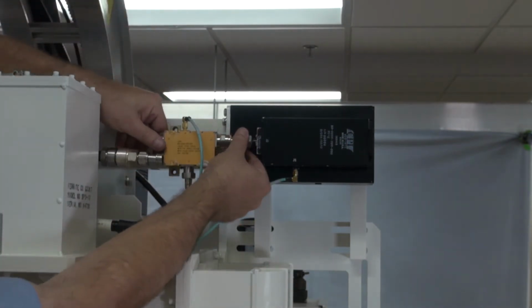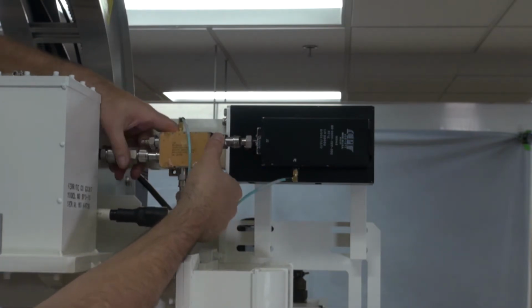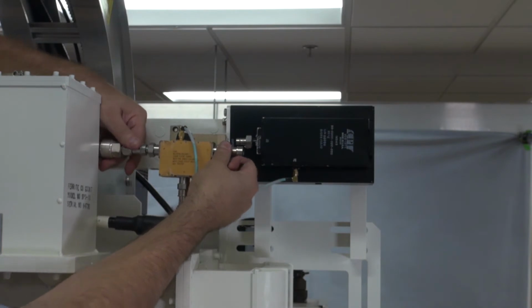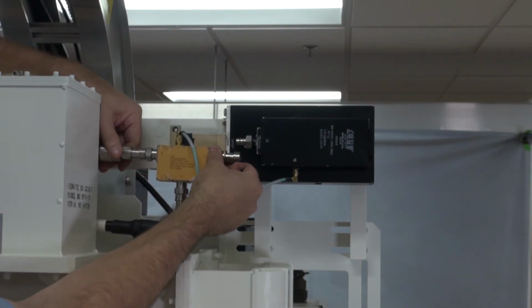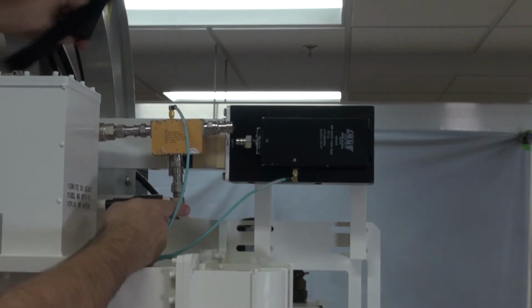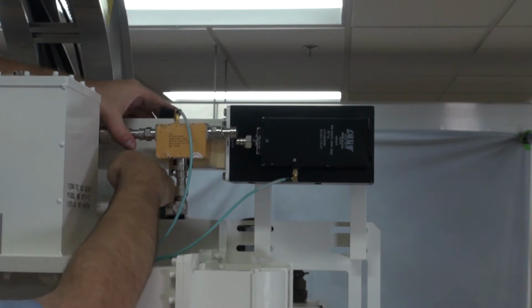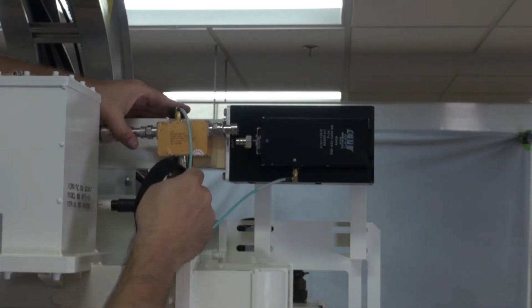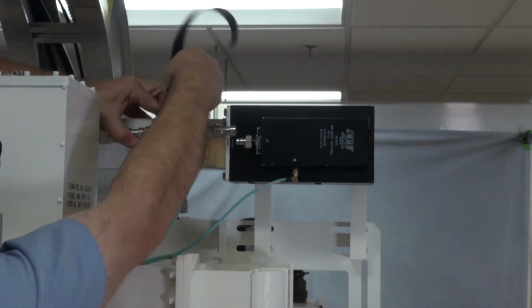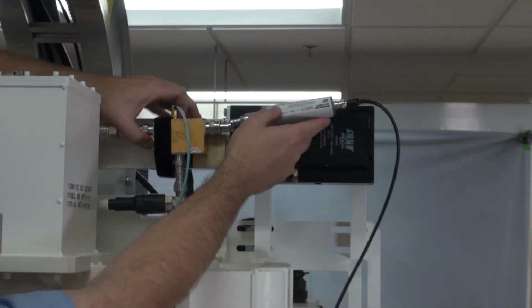Disconnect the LNA from the TR limiter. Reconnect cables 2W556 and 2W577 to the LNA. Connect the noise source to the input of the horizontal LNA.